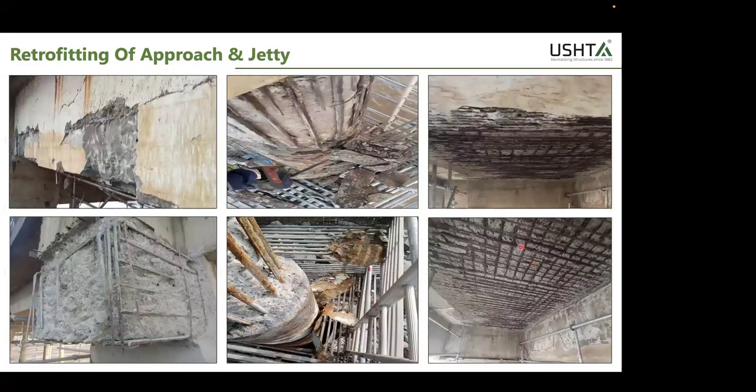So see, this is how the system did not work. They added one layer of concrete here. However, in the beam, they did jacketing, but the jacketing separated from the original concrete. When we dug deep into that, we realized that the grade of concrete they had used was very high. They used almost M60, M80 grade of micro concrete. Now that is not compatible with the original concrete.